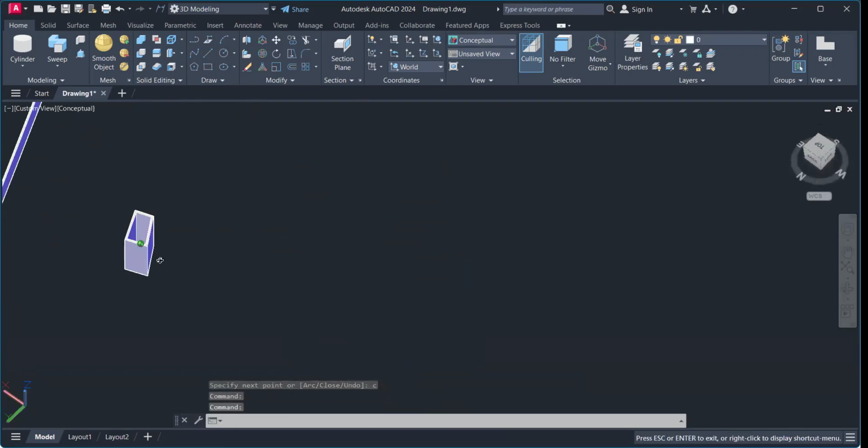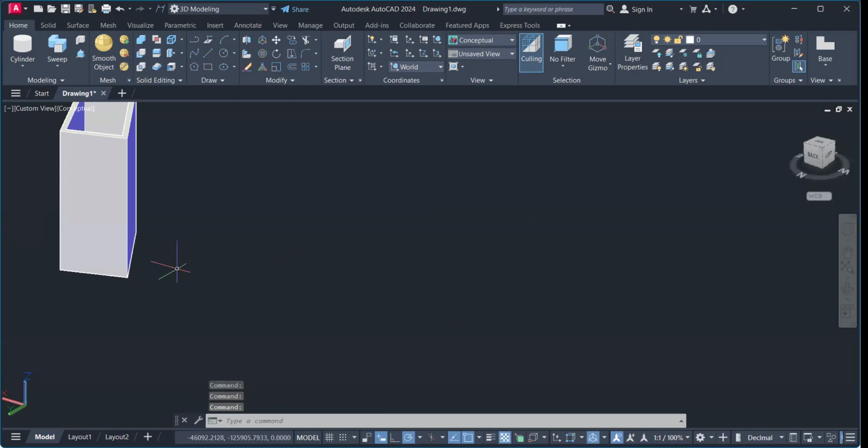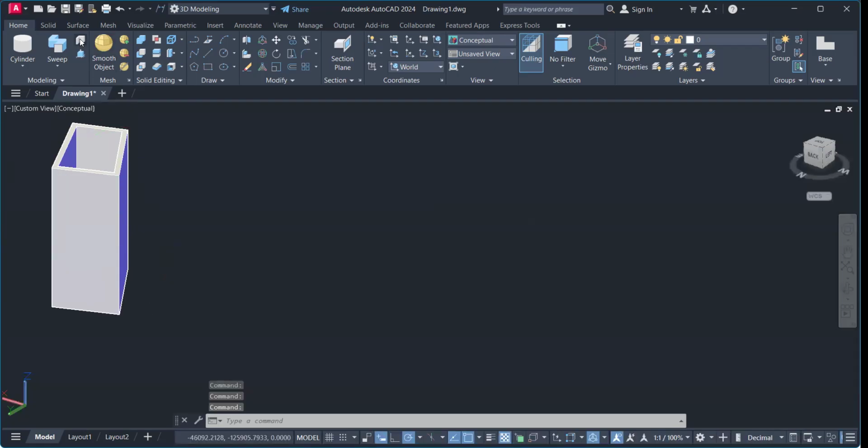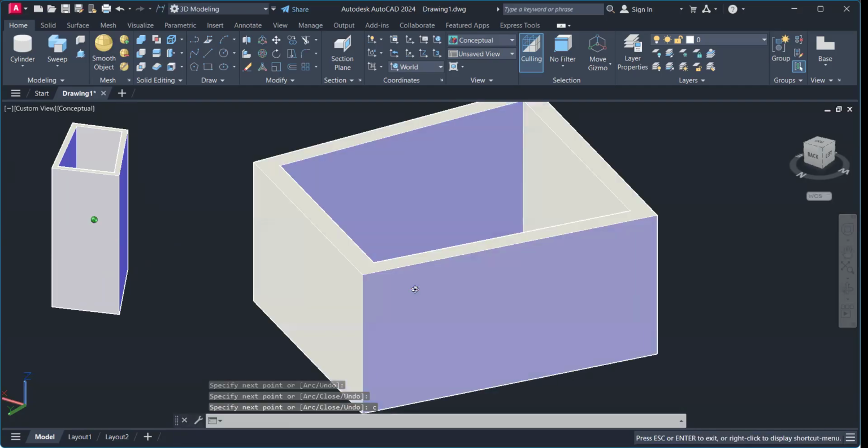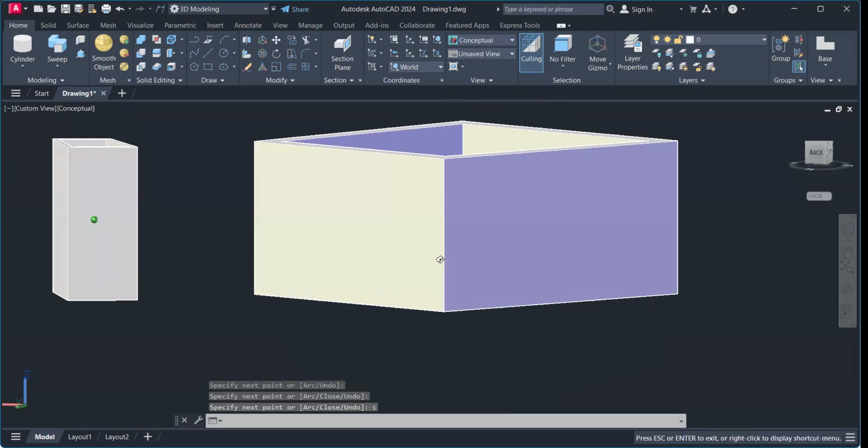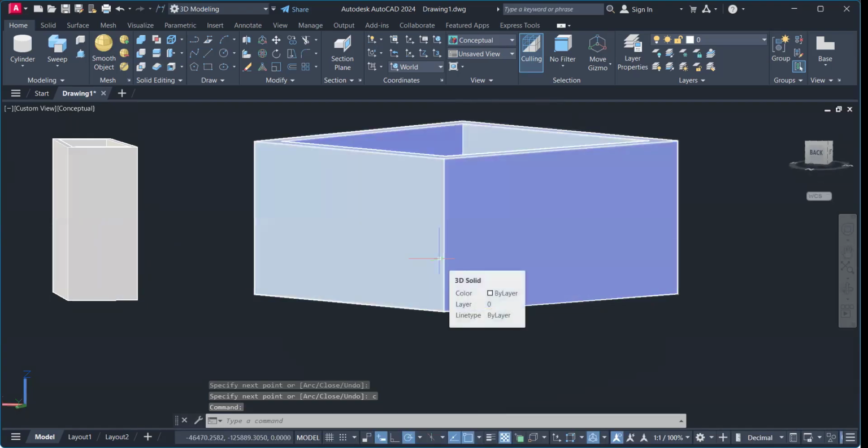Okay, also you can specify thickness. How can we specify thickness right here? Select polysolid, and then this is my width section also, enter, and then here I increase the width to 20 mm. Okay, then what will happen, my wall thickness increases, right? And this will be greater. Enter, okay? And then you can create this type of thing. Now, this is a simple way you can use it. So you can increase the height of the wall and increase the thickness of the wall.